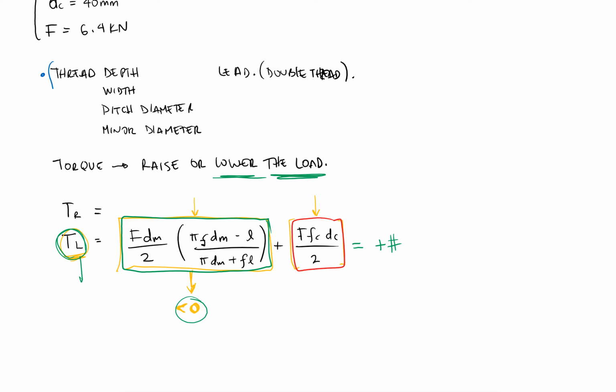We're going through all the dimensional ones, the torque to lower, and then the other questions would be the stresses, all of them separately. So the torsion, the shear stresses, sorry, the normal stresses, the bearing stress, that's going to be also important. And then from these, get a von Mises stress at the critical stress element, which is the one that we identified, right?